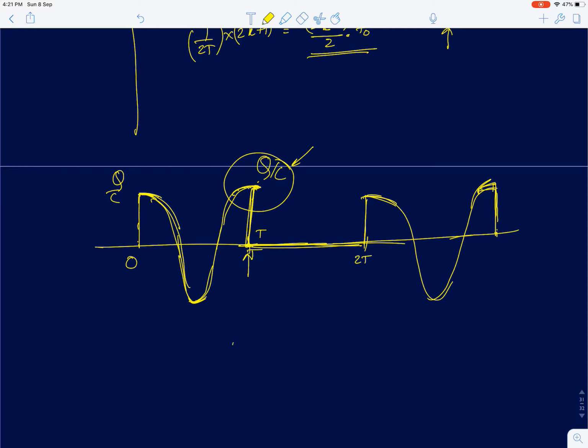So when you feed a frequency which is exactly equal to the resonant frequency, you will always be adding energy to the tank, both in the positive and negative half cycles. So therefore the tank will keep on storing the energy. And since it's a sinusoid, it's everlasting, it will exist for all time. You will be transferring energy continuously. Eventually the energy in the tank will also blow up to infinity. So the amplitude of the sine wave is also going to blow up to infinity. So this is one intuitive way of explaining it.